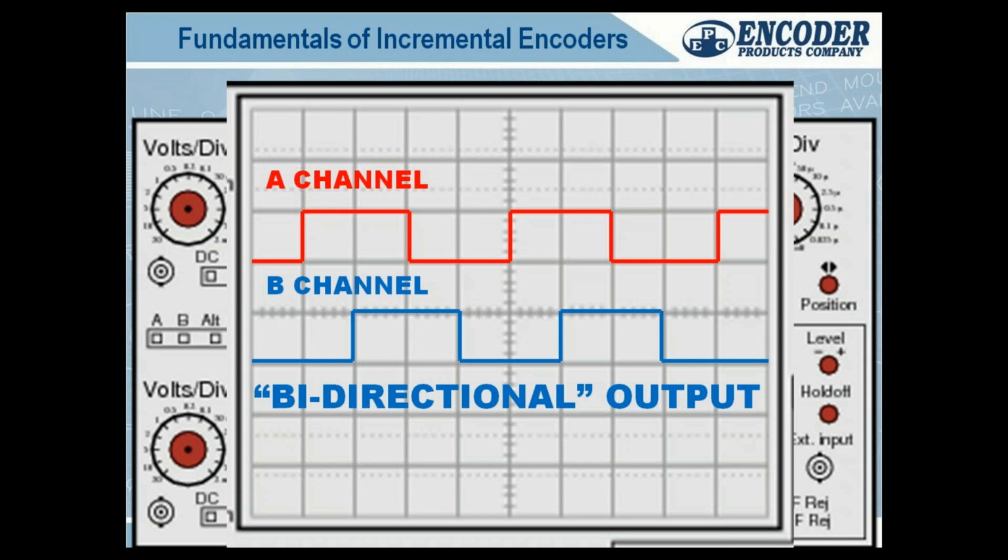But as soon as the signals look like that, because it swapped direction and B rises before A here, we have B and then A, your PLC control is going to know, okay, subtract. So, oh, it moved out, oh, it came back, and this is subtract. B leads A. So that's the purpose of bidirectional output.